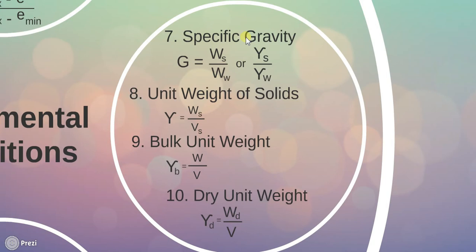And if all internal voids of soil particles are included in the volume of soil solids, the specific gravity obtained is called mass specific gravity. Moreover, absolute specific gravity is also known as true specific gravity, and mass specific gravity is also known as apparent specific gravity or bulk specific gravity. There is little exception in the range which was given, 2.65 to 2.8. The organic soils generally have specific gravity less than 2.0. There is one exception.